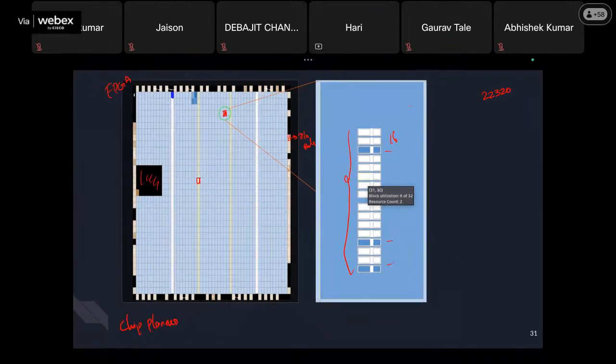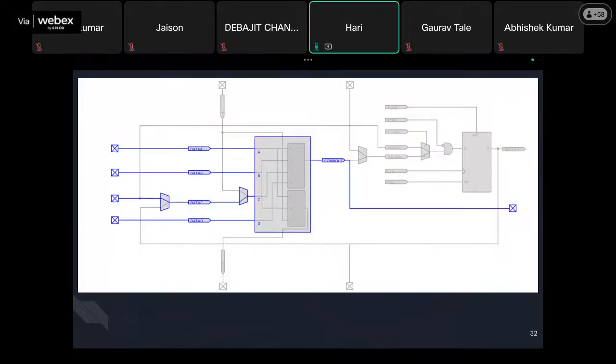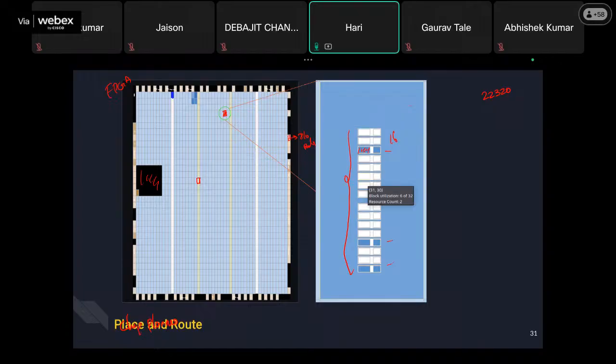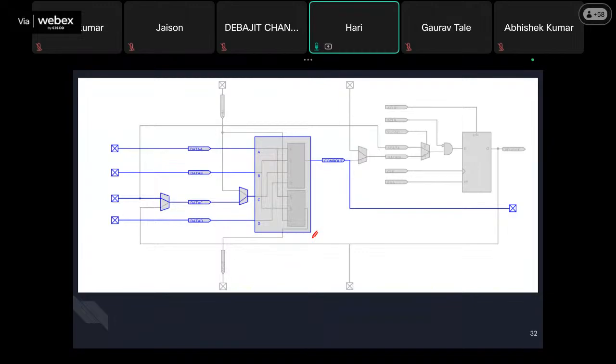So these things are there. If we have a close look, this particular small logic block has this much amount of logic elements, and inside this particular logic element we have this particular LUT. As I said, one configurable logic block has a LUT, one register, and a multiplexer, right? This is a four input LUT. We call it a four input LUT. It can vary in number based on the design of an actual FPGA, based on the manufacturer. This four input LUT will have the LUT mux and everything defined inside it.